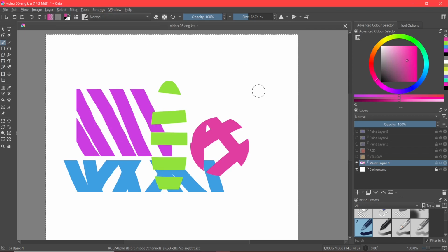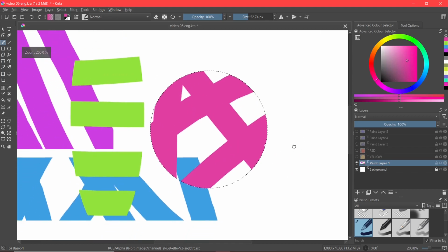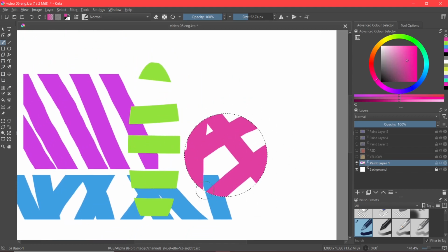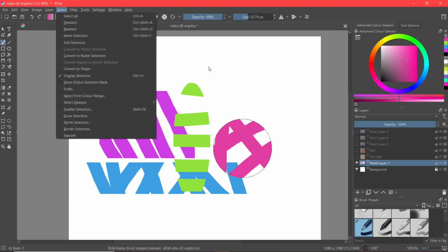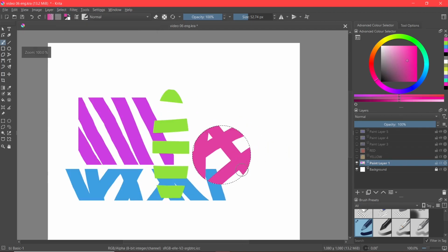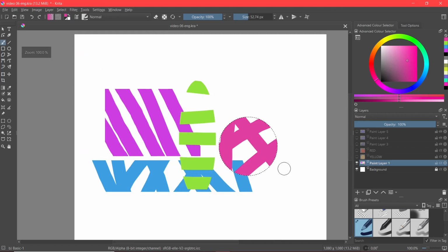So we can do that by, first of all, we can go back. So let's click Ctrl Z and go back to the selection of our little circle here. And then we can try the Reselect option. So Ctrl, Shift, letter D. So we can do this by, first of all, switching off this selection, and it is Ctrl, Shift, letter A. Selection is turned off. And now if we try typing on our keyboard Ctrl, Shift, letter D, the same selection will reappear. It will be selected again.